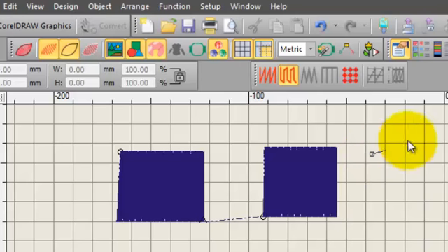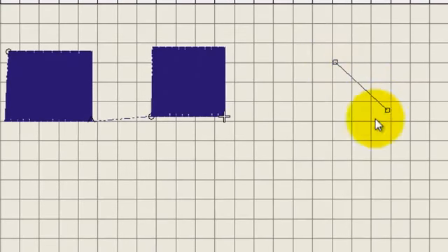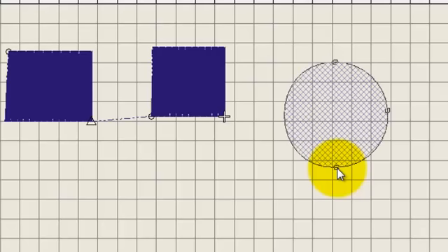Left click, control. Well, actually, we'll do a circle this time. So let's go back. Right click, right click, and hit enter, and the shape will be completed. Now I'm going to cut a couple of holes out of this shape, so before I hit enter once again, I'll just digitize another shape inside the circle, and you can see the cross hatching disappears.